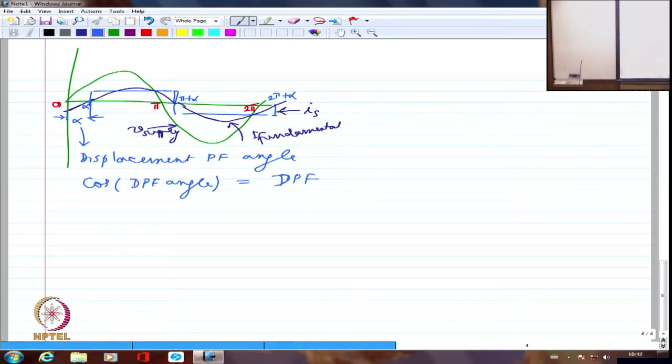So the thyristor converters in general have a couple of problems. One problem is always the converter circuit, even if I connect a simple resistance, in all probability I will ask for some amount of reactive power. The circuit will demand some amount of reactive power. Right? So it is going to demand a certain amount of reactive power because the displacement power factor is not unity.